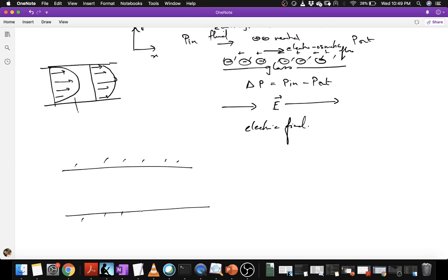So these are my walls. I have a pressure-driven flow of the fluid, but at the walls I say that there is a slip velocity. In other words, you can imagine a flow where you have flow of fluid, but the walls themselves are moving. Even though in reality the walls are not moving, a thin layer of fluid moves near the wall.